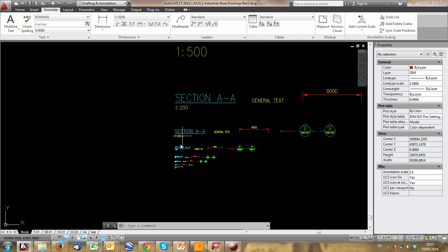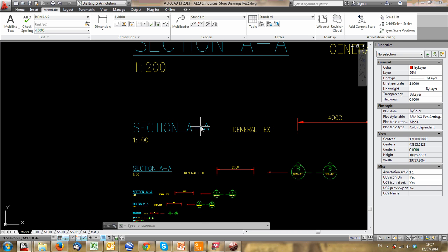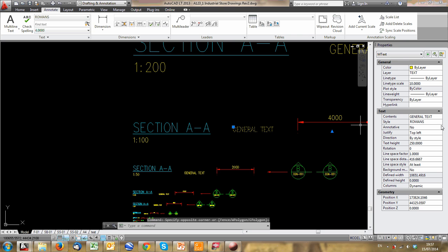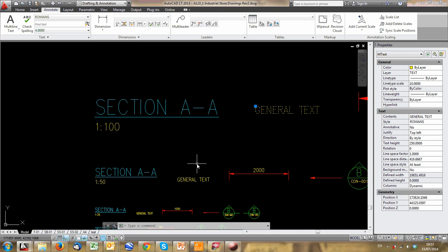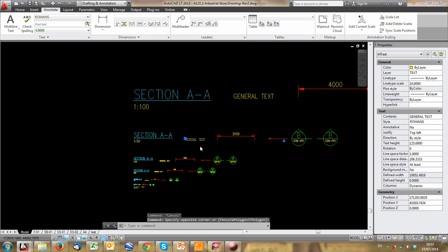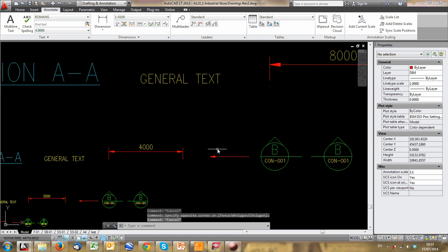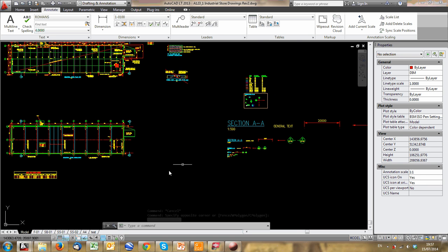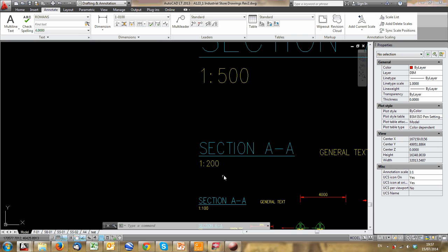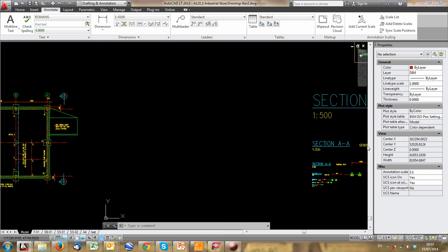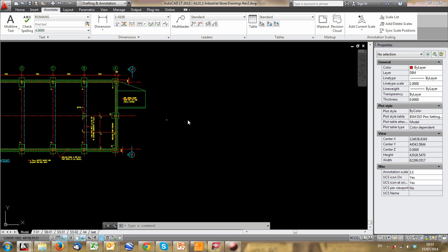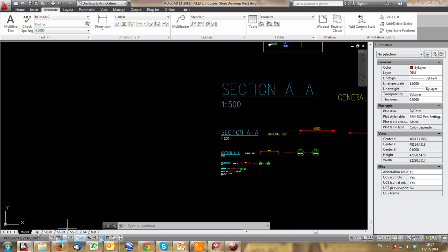And also you set up a text style, and then you can just copy it up or down. Rule of thumb, I know a 1 in 100 is a 250 millimeter text height, and then I can just adjust it from that. So obviously a 1 in 50 is a 125, and it goes down through all those. So you can set that up. You can have your section marks, your leaders, and all sorts of details set as constant. And then you just copy and paste this for 1 in 200, 1 in 500 to the drawing you're using, such that you've got all the information then and there. So it allows you to draw.